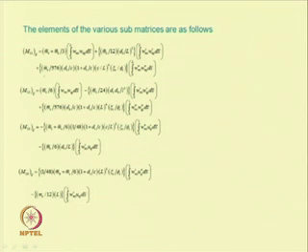Similarly, this is plus m_c bar by 576 into d_t by c into 1 plus d_t by c into (c by L) to the power 4 into zeta_c by phi_c into integration 0 to L W''_mi. So, this is double dash. Single dash is single differentiation with respect to x, and this double dash is double differentiation with respect to x. Similarly, one can find M12 using this expression, M13 ij can be found from this expression, and M14 ij can be found from this expression.